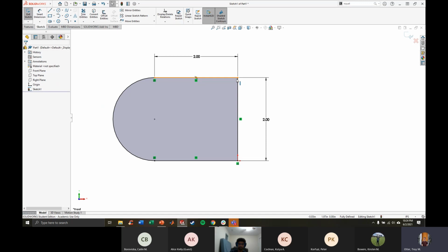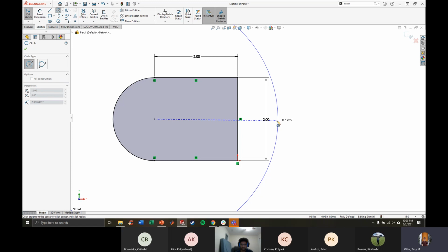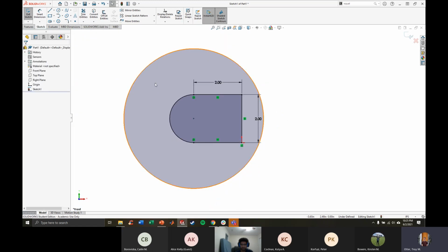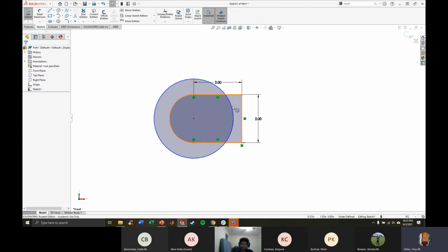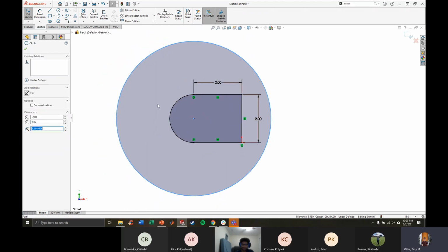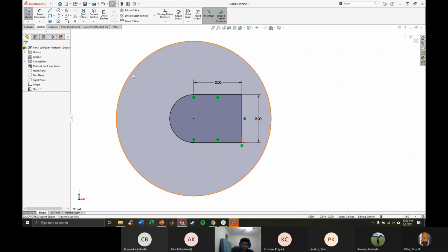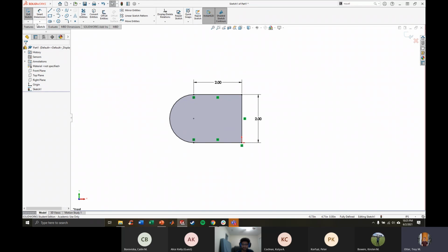So yeah, this is pretty much all you want to see when you've created a sketch, a closed area, shaded in the middle. And you can have things that are doubly shaded. Like, I'll close this within another circle. This part is still shaded, and when I go to extrude I can choose which area I want to pull out. Let's say I wanted to make a circle with a cutout in the middle, I can just choose to extrude this outside shaded area instead of the whole thing. But I'll do that for now. And yeah, you want to make sure that it is fully defined.